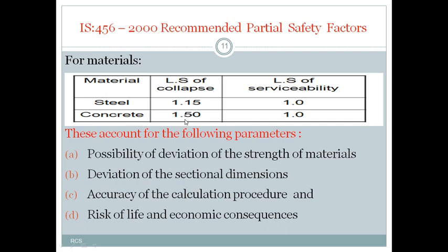That means we are manufacturing concrete on an open site. The temperature is different, humidity is different, right? You may have some inferior material, and sometimes we human beings may mix the concrete in different proportions than required. So at the end of the preparation of concrete, if you test the concrete, you may not get the required strength. That's why we are using a higher factor of safety for concrete than for steel.